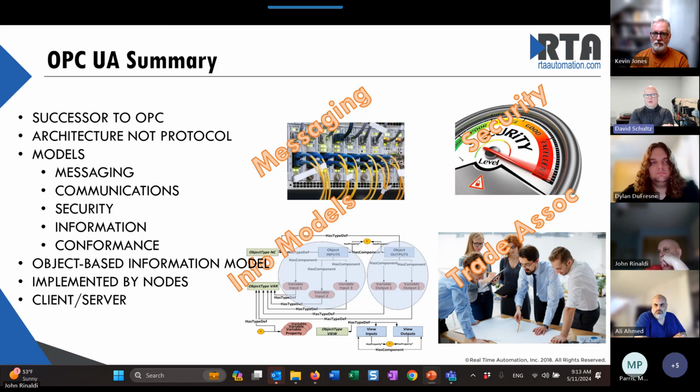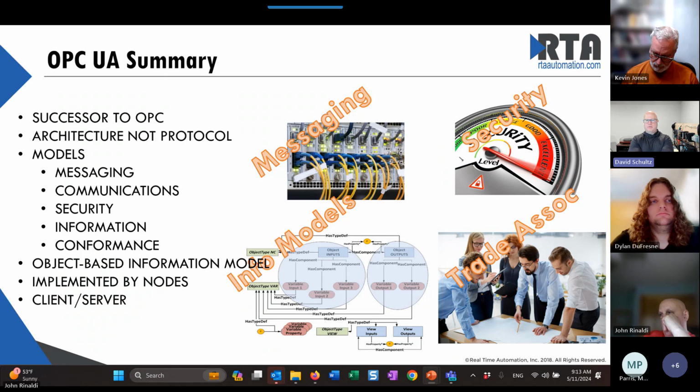It'd be interesting, because one of the first standards that came out of ISA was around instrument objects when you're doing P&IDs. I think it's ISA 5. And it's almost like, can't we just take those things and decide, okay, this is now how you're going to do tags for this type of equipment, and it's going to have these basics. This is your core model. It shall have it to meet this standard, and you want to use this type of tag naming convention. I think that'd be pretty slick, but I don't know.